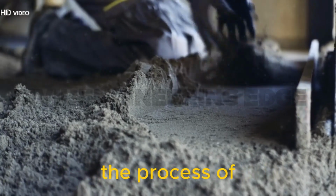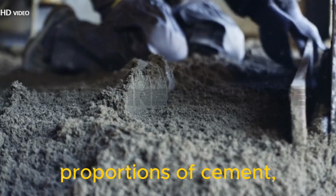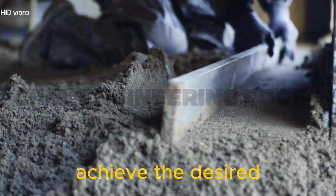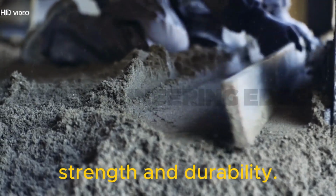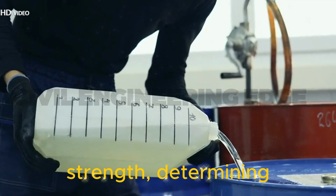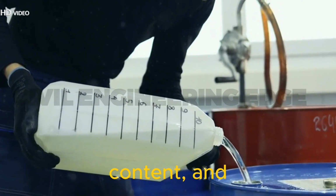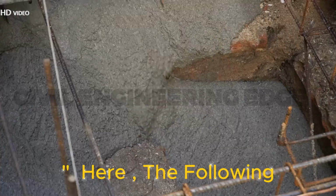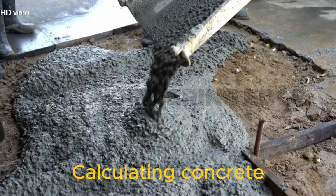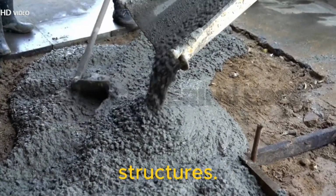Concrete mix design is the process of determining the right proportions of cement, water, fine aggregates, and coarse aggregates to achieve the desired strength and durability. The key steps include calculating target strength, determining the water-cement ratio, selecting water content, and proportioning the aggregates. Here, the following steps are involved for calculating concrete mix for reinforced cement concrete, RCC, structures.